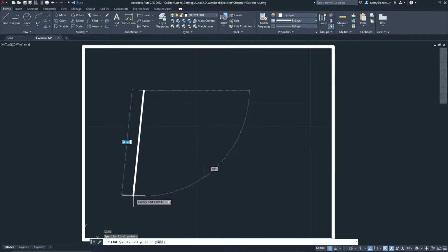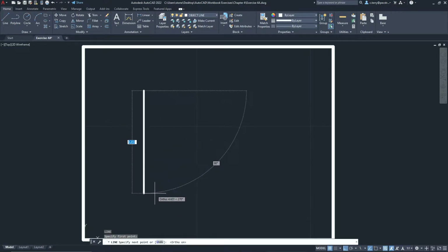So let's go over them. If you draw a line, and turn my ortho on using F8, and I want to draw another line. Right now, my object snap is turned off. If I hit the F3 key, or if you come down here, snap cursor to 2D references, or you can type in the command OSnap. I like using the keyboard, it's much faster. So I'm going to hit F3 to turn my snap on. If you notice, there's a little bitty green square at the end called endpoint. That's the first snap we're going to cover.